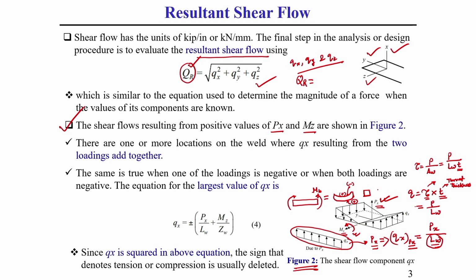If you take a section, let us say a square or rectangular section, how will the bending stress look in this section? The bending stress will be negative maximum at the top, generally 0 at the neutral axis, and positive at the bottom side. You know this very well.